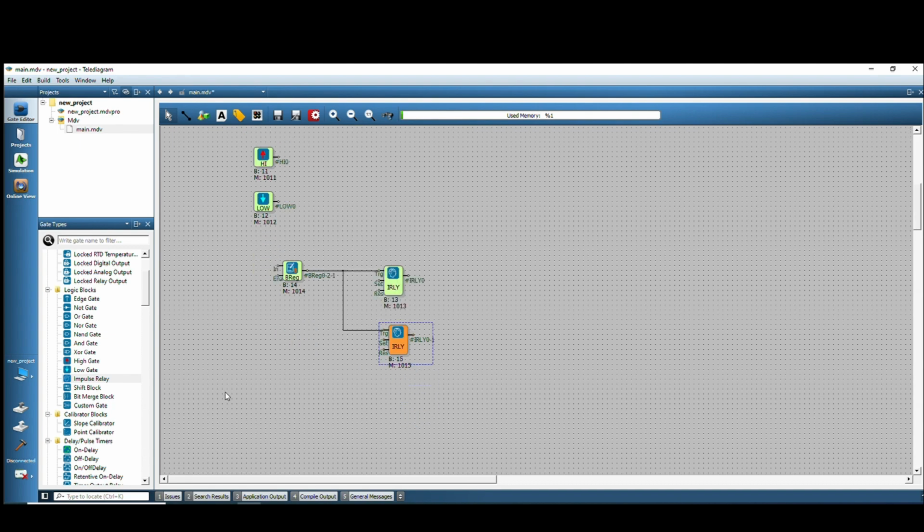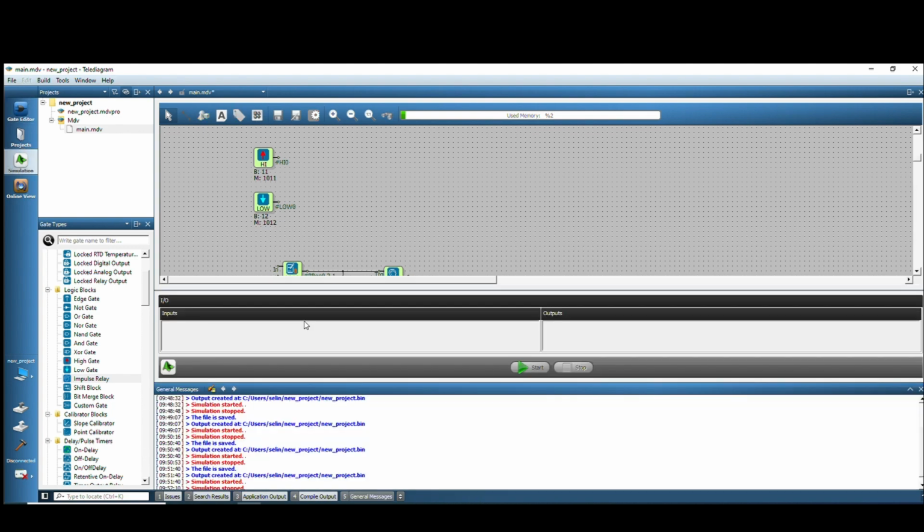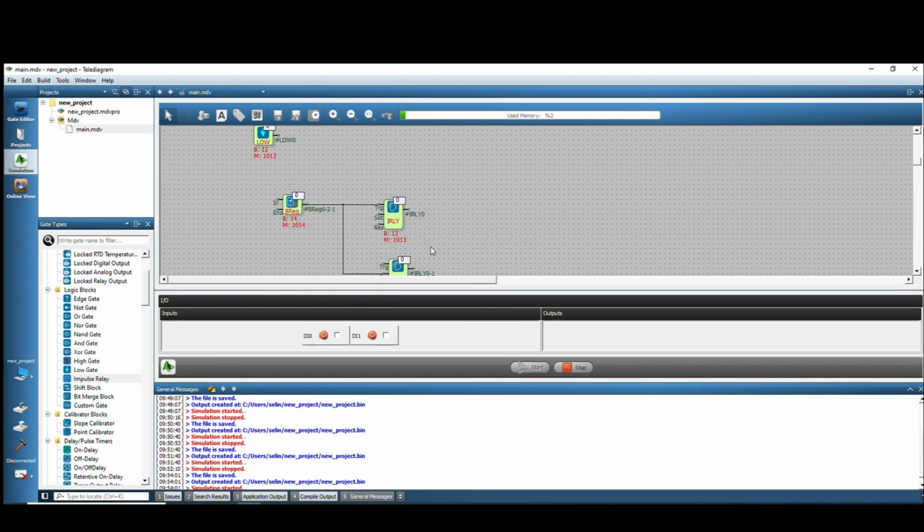When the set block input is high, 1, regardless of the position of the TRG block input, the block output is high, 1. When a rising edge trigger is applied to the res block input, the block output always transitions to low, 0. When the res block input is high, 1, even if other inputs... Let's watch this situation with the simulation.